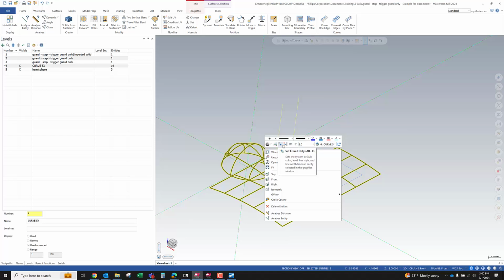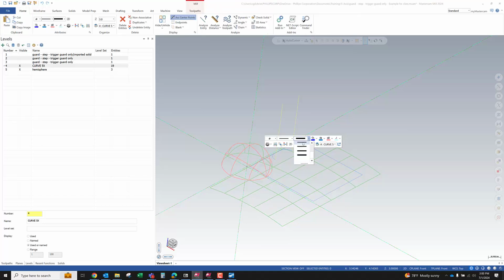There's an option in here for multiple attributes on the selected entities. A lot of these are single entity attributes, right? I can change point style, line style, line width. As an example of one attribute that's built in here, I've got these selected. I'm going to change to a thin line style display, and I exit the menu.